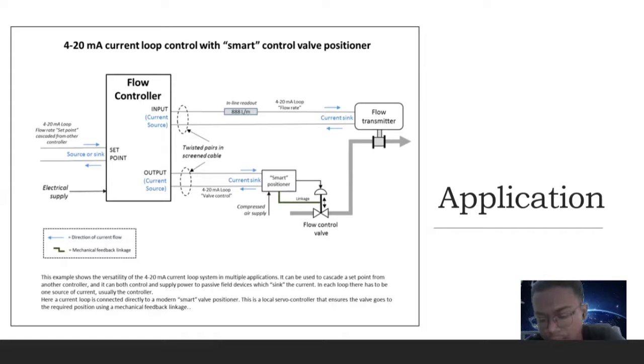To reduce the effect of this load disturbance, sensors and transmitters collect information about the process variable and its relationship to some desired set point. A controller then processes this information and decides what must be done to get the process variable back to where it should be after a load disturbance occurs.